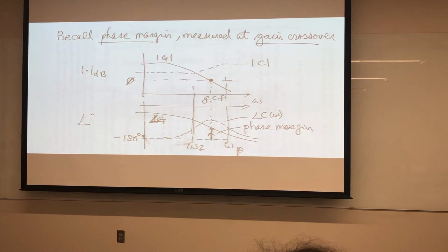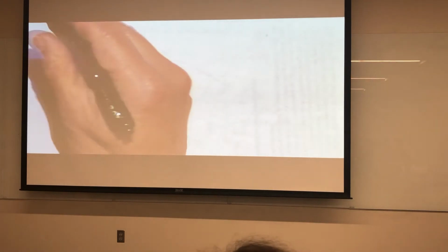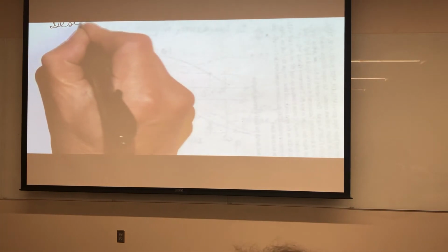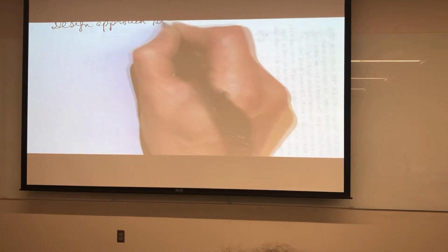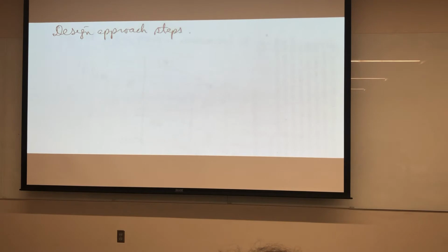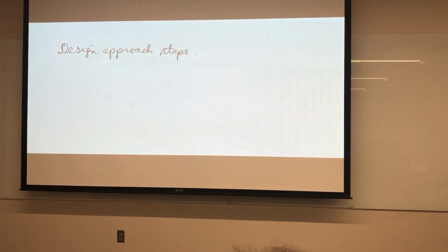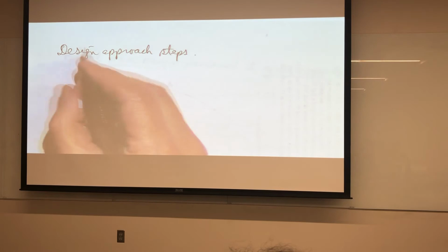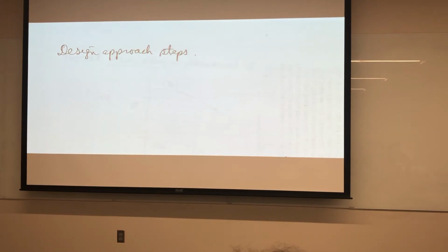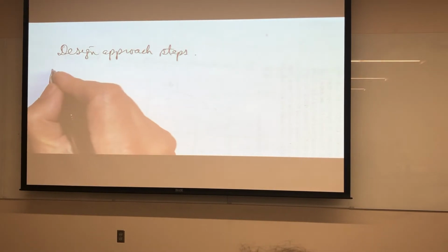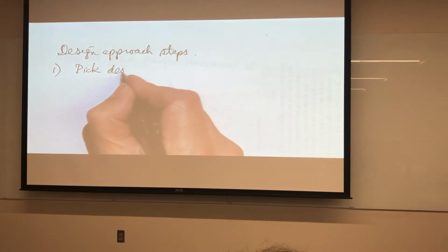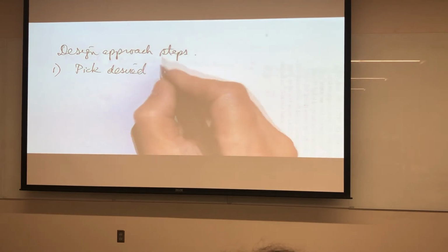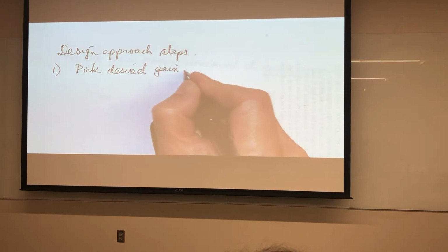Okay, so this is the design approach. Let me summarize the design approach. So the first thing we'll do is we're typically given a high frequency specification. So what we do is we pick the desired gain crossover.